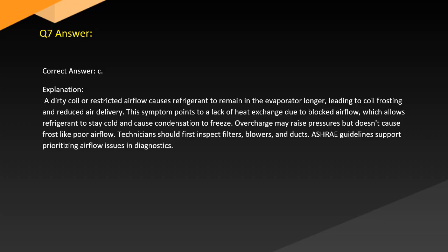Overcharge may raise pressures but doesn't cause frost-like poor airflow. Technicians should first inspect filters, blowers, and ducts. ASHRAE guidelines support prioritizing airflow issues in diagnostics.